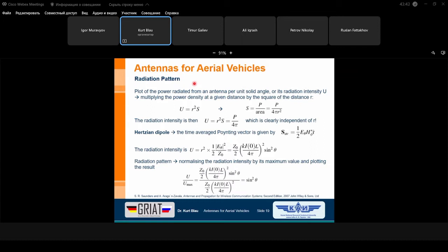We can say, okay, let's use the antenna mounted on a mast or on a tower, and then we can take a drone with a sensor. It's a very small receiver, and this receiver can detect the measured field strength values or incoming power and make a record in a memory. You can imagine this.